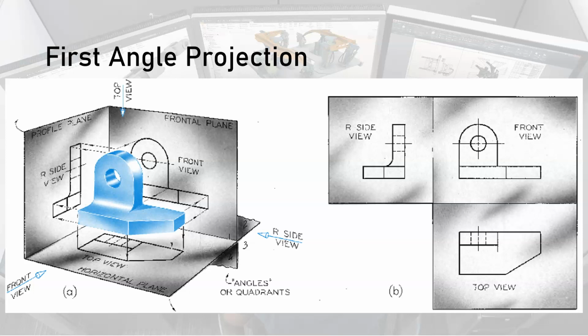Fusion will do that for you, and if you're interested, you can play around with that. What you would have to do, and we'll talk about this when you look at the drawing videos, is choose a European standard. So instead of the ASME standard, you would choose the ISO standard, and then it will automatically generate the first angle projection views. All right. So let's finish up here. We just have a couple more slides.